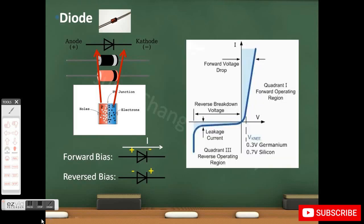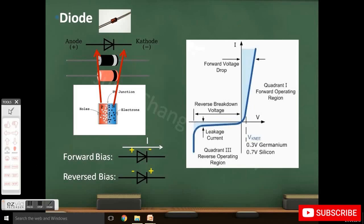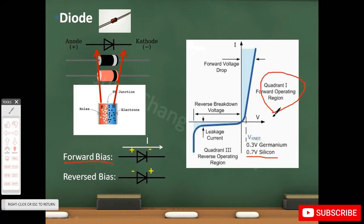This graph shows the characteristic of a diode. For a silicon diode, a typical forward voltage is 0.7 volts, meaning that if the diode is forward biased and the voltage across the diode is greater than 0.7 volts, the voltage will be capped at 0.7 volts and the diode acts like a short circuit.